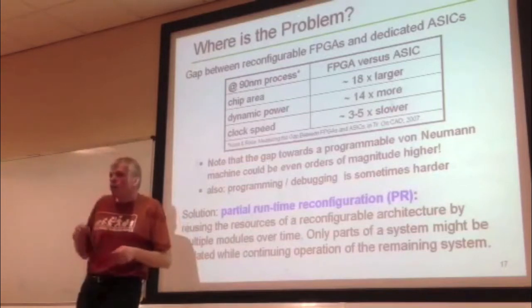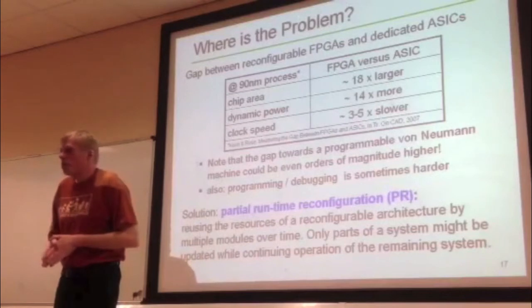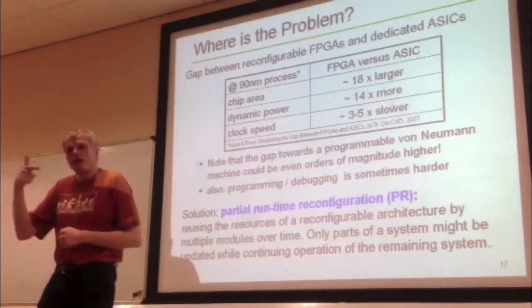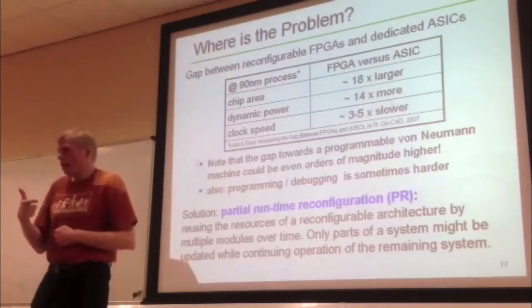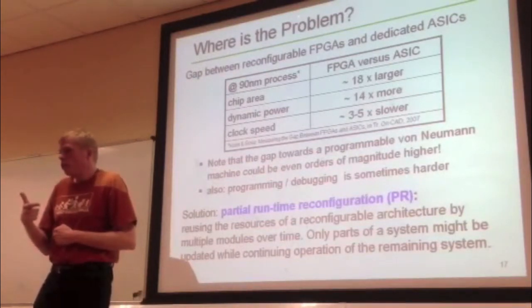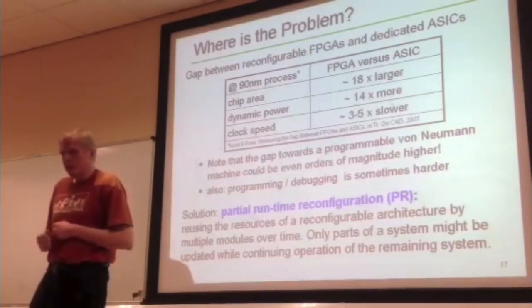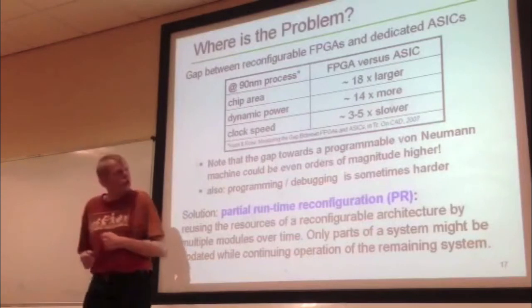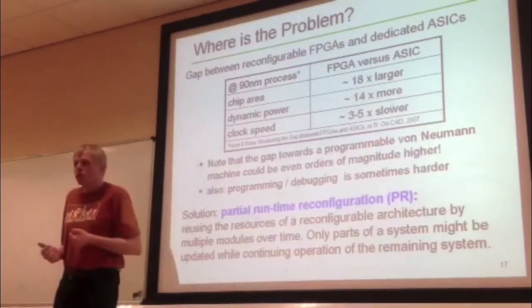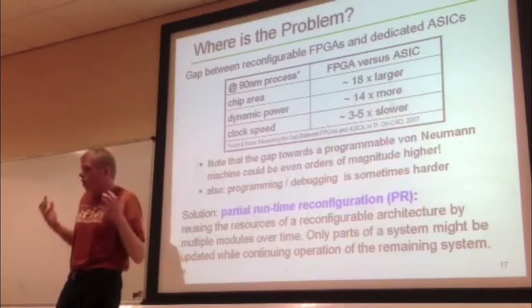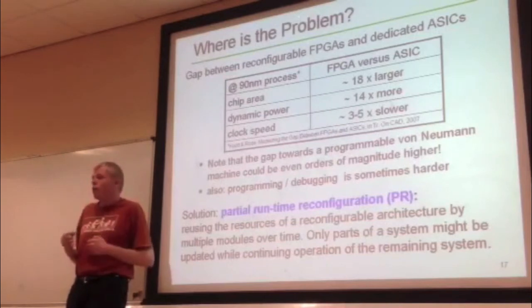For example, if you consider a processor, it has, let's say, 100 different instructions, but each clock or operational cycle, you use just one of the instructions. So all the rest is pure overhead. If you only use load and store, let's say for memory movements with your processor, you use only very little of the whole functionality. You won't use the floating point unit. This would be pure overhead. So in other words, having things programmable always comes with an overhead.